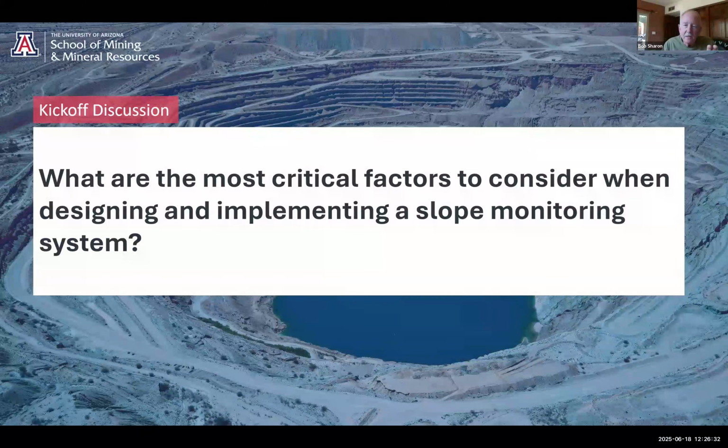But I think a lot of the geotechnical people out there, the slope engineers at a lot of the operations, still continue to not really be able to utilize the power of the information that they can get. For example, a lot of mining operations are still collecting only slope distance data from their prisms. They're bringing prisms up, but from a number of clients, maybe half of them, all they're showing us is slope distance. We're not getting the vector components.